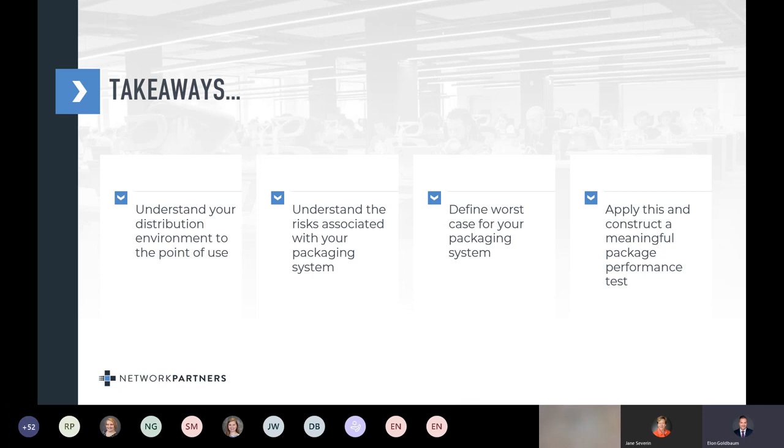So what we would say is we would evaluate the whole system under worst case circumstances. So what does that mean? Wes Bush gave a great webinar prior to this one on defining worst case. So worst case geometries, mass, pack factors, even down to the seals, all the seals, like your supplier seals and the MDM manufactured seals, so you get worst case seal strength. So you know that you're testing based on this sample size of 58 that it's going through worst case everything, and you can prove out at the end that it still maintains sterile barrier integrity and what it's supposed to do.